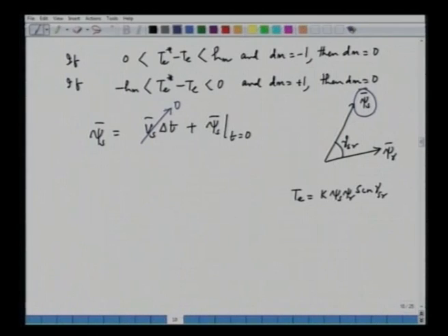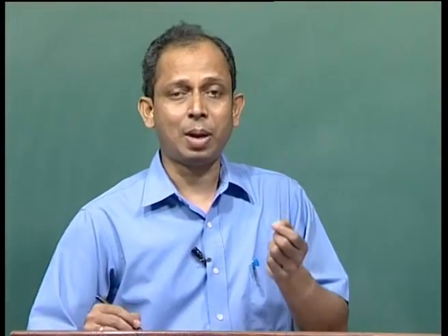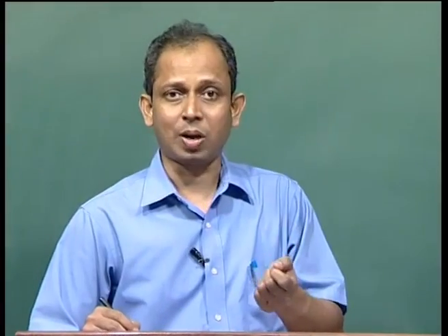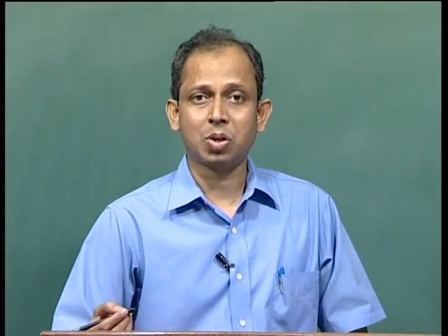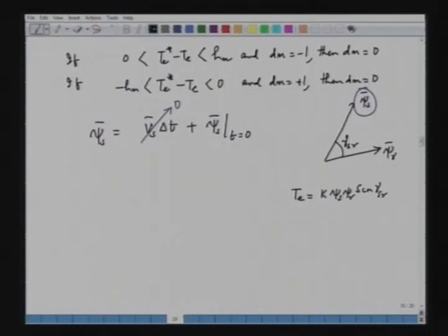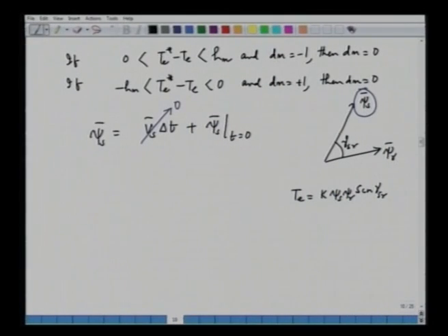So, suppose we apply Vs equal to 0. If Vs is equal to 0, the flux is neither increased nor decreased. We know that psi s equals psi s at t equal to 0, because we have applied a 0 voltage vector. So, by applying a 0 voltage vector, we are freezing the flux. It means the torque is neither increased nor decreased. So, that is how we can maintain the status quo of the torque unchanged. So, this is about the various status of the flux and the torque.